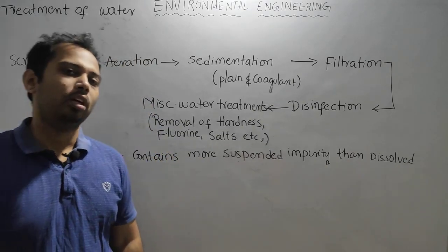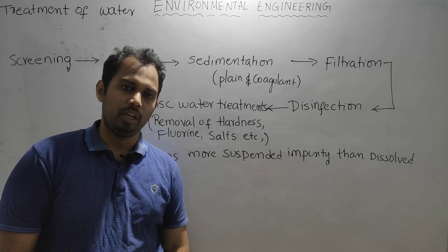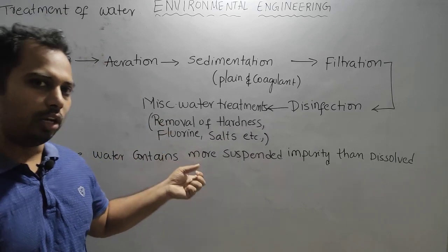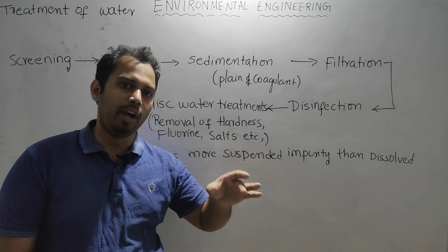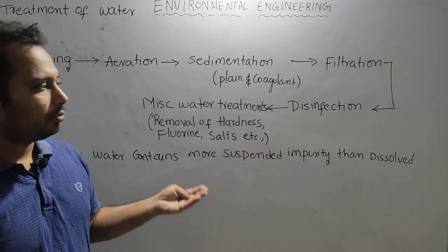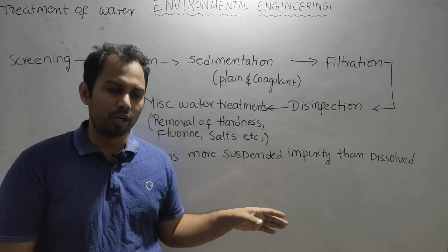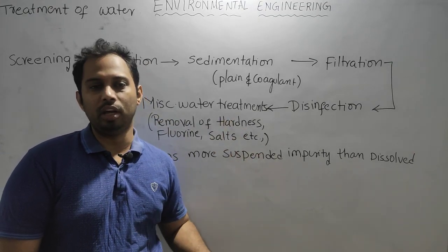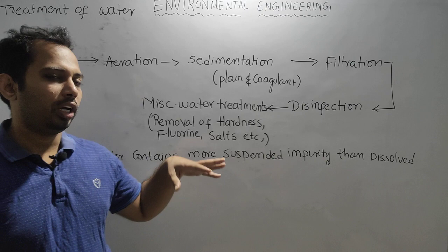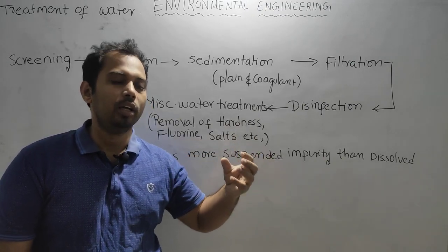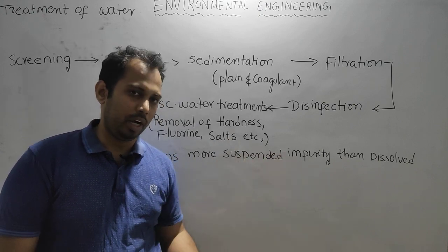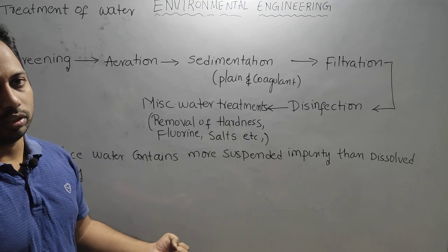If calcium is present anywhere in nature, then this CO3 2 minus will react with calcium and become calcium carbonate precipitate. Similarly, iron ion in water will find some OH minus ion and become Fe(OH)3 precipitate. Likewise, dissolved impurities, when they get an oppositely charged compound, will react with it and form precipitate. Once they form precipitate, there are no more dissolved impurities.